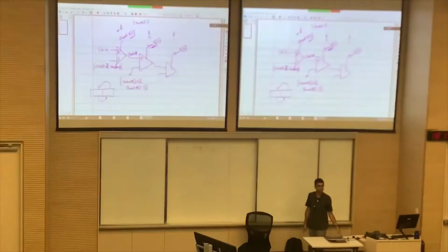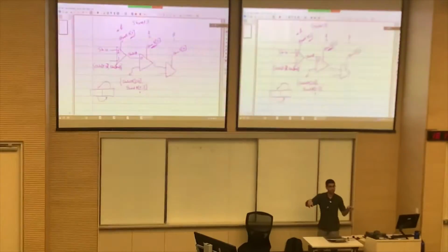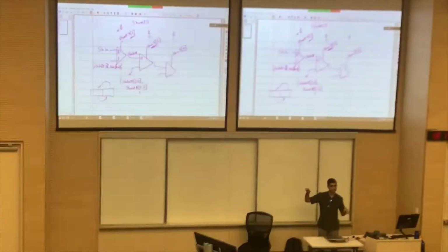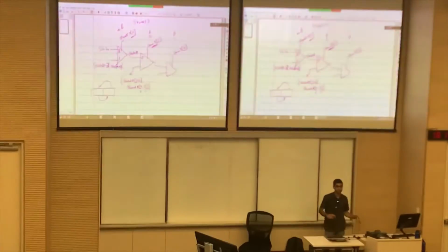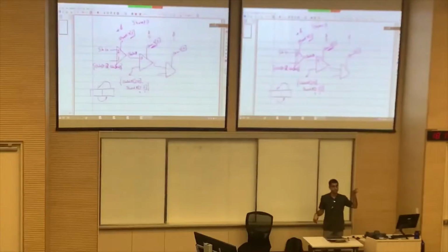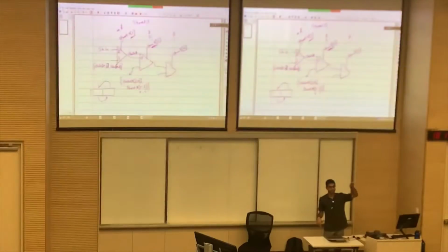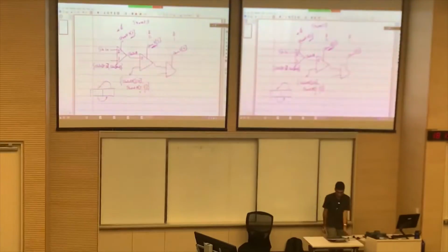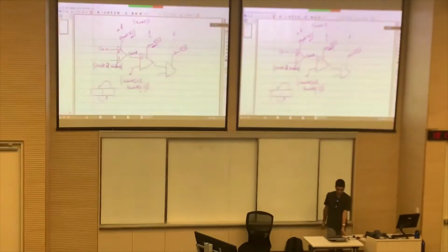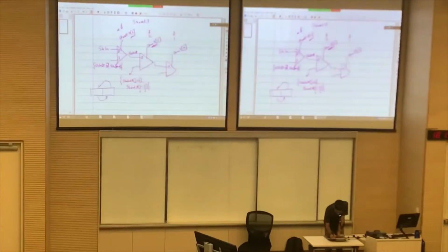So this is rotating right by 2 positions, so that your original bit number 7 now becomes bit number 5, right? And original bit number 2 becomes bit number 0, and original bit number 1 now becomes bit number 7, and original bit number 0 becomes bit number 6. That's the idea. And same here.